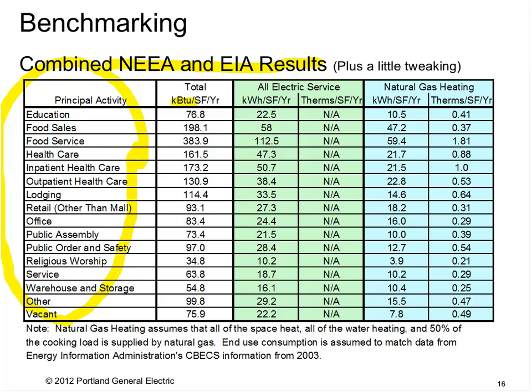But if you then try to look at a refrigerated storage warehouse, a non-commercial type occupancy, it's going to depend on what type of refrigerated storage you're doing to then determine what your benchmark of energy consumption should be. If you've got real cold temperatures you're trying to maintain, then you're going to consume more energy than if you're trying to maintain a warmer temperature. Enough said on that. So in the column here, we've got kBTU per square foot per year.